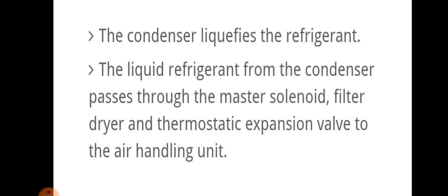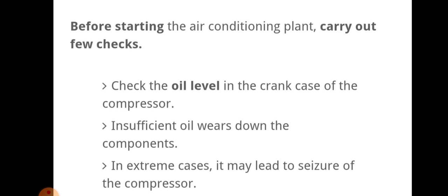The condenser liquefies the refrigerant, and the liquid refrigerant from the condenser passes through the master solenoid, then to the filter dryer, and finally to the thermostatic expansion valve to the air handling unit.